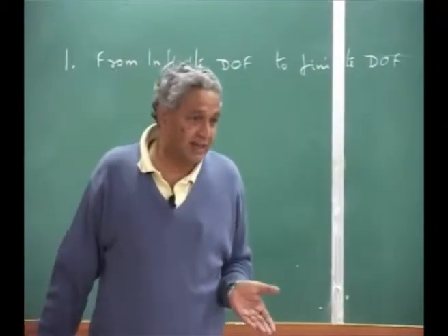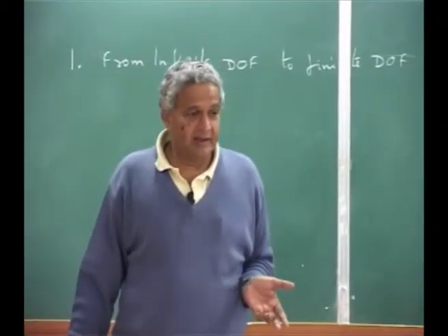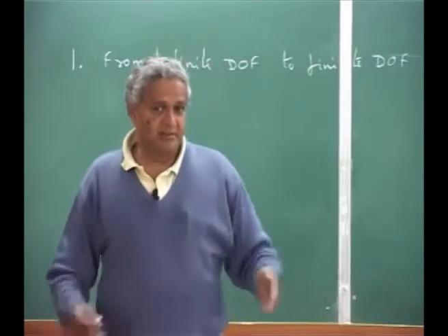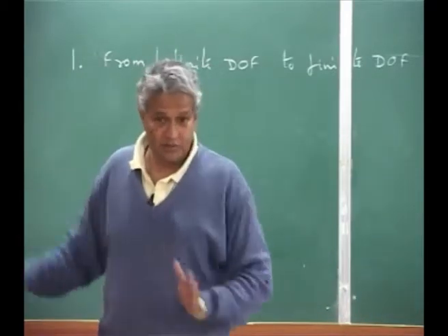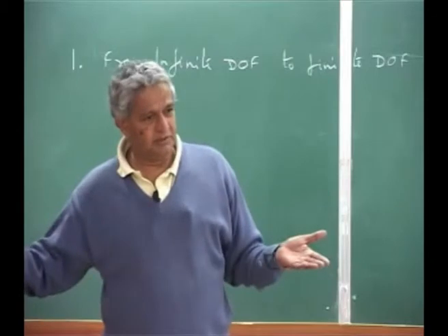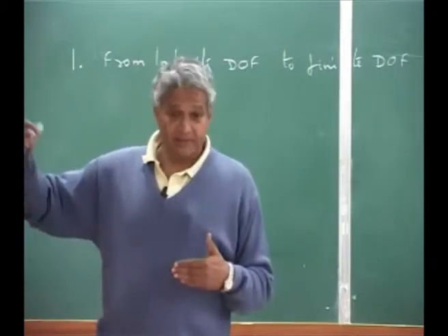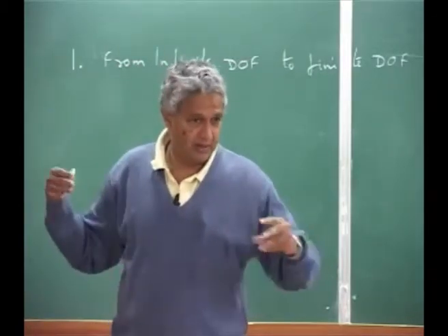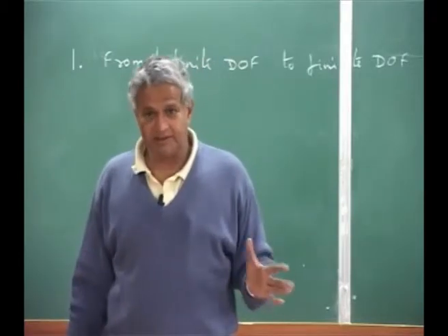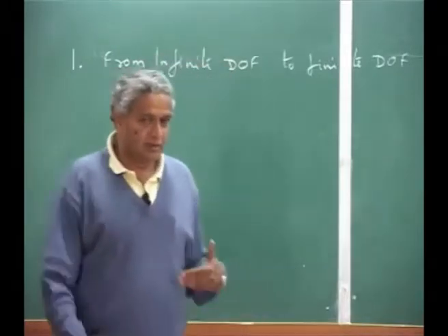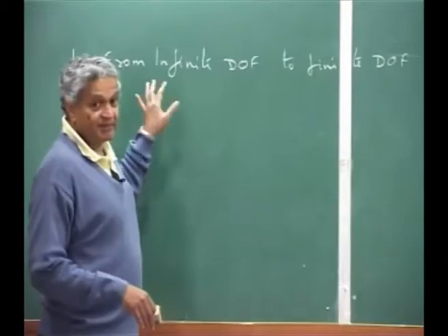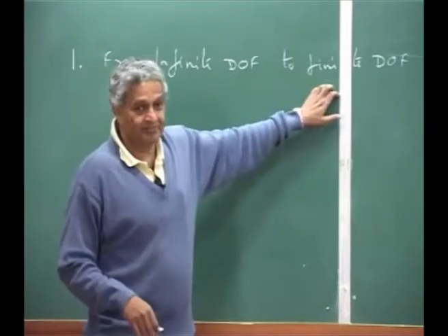Whereas in the case of an aircraft wing, in some industry calculations they may take about 40, 50 or 100 modes. Is it really necessary to have higher modes? That depends on how accurately you want your results predicted. Okay. So this is the reduction of an infinite to finite.